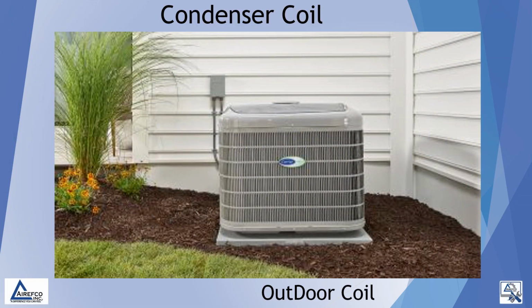For years, we have called the coil in the outdoor unit the condenser coil, as that designates the work this coil does. With the introduction of the heat pump in the late 70s, we started calling the coils on a split system the outdoor coil and the indoor coil, because with a heat pump, the function of the coil changes depending on what mode the heat pump is operating in. In the cooling mode, the outdoor coil functions as a condenser, and in the heating mode, the outdoor coil functions as an evaporator.